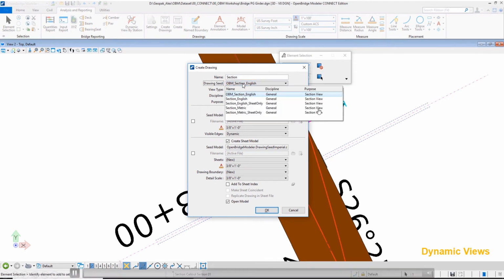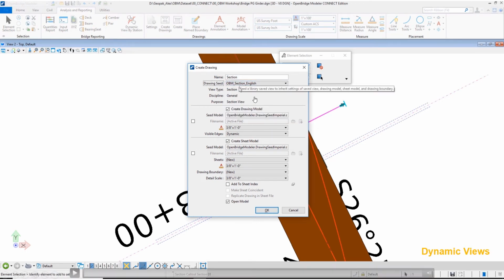And then here comes your definitions as all these drawing sheets, they are DGN files, and where your sheet border will be generated to, it needs to be set up. You need to configure this in OpenBridge Modeler. OpenRoads Designer, for example, it has its own configuration too. So to accommodate what size of border you want to use, what type of border you want to use, and all of that, depending on the scales you use. So you need to configure that. But when it's done, for the standard operator, it will be just a matter of selecting the scale, the size, and we say, well, let's proceed.